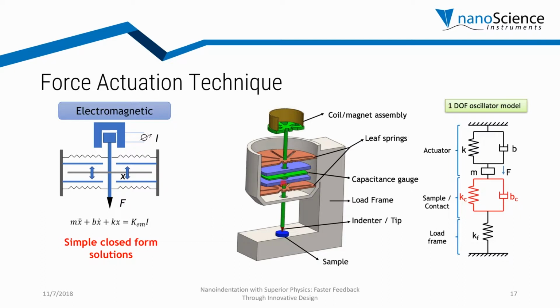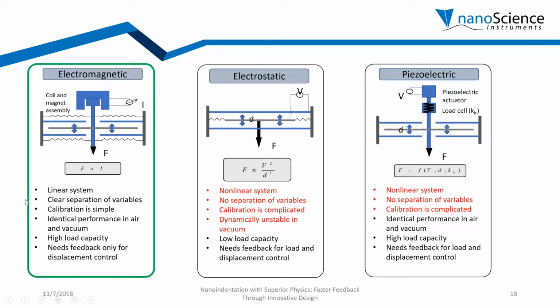So while this indenter is moving, we are precisely measuring the change in the capacitance, and that's how we know how our displacements are into the surface. So this is a very simple and robust model to measure both loads and displacement. Now, there are some other ways to perform these measurements, but there are some real problems associated with them.